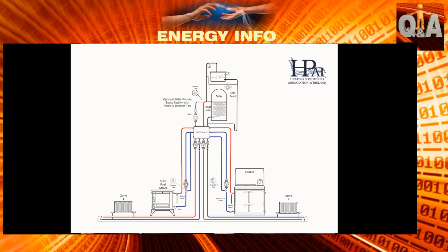And what's that there then, just here on that half-inch pipe coming across? That's a non-return valve. Sometimes it's needed, sometimes not. It would face towards the cold feed so that it doesn't allow water to circulate backwards. Oh, I'm with you. It's only if water builds up in the expansion. It is a flap type, isn't it? It's a flap type valve fitted on a horizontal pipe. So the gate has to be flat? It just barely opens on a horizontal pipe. Oh, yeah. There's no point having it on a vertical pipe because the gate would be too heavy and the gate would hang open anyway. I'm with you.